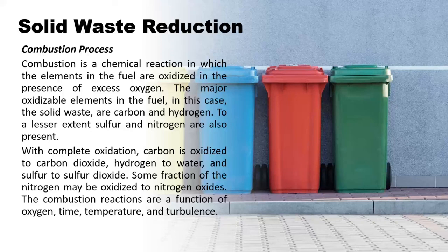Combustion is a chemical reaction in which the elements in the fuel are oxidized in the presence of oxygen. The major oxidizable elements in the fuel, in this case the solid waste, are carbon and hydrogen. To a lesser extent, sulfur and nitrogen are also present. With complete oxidation, carbon is oxidized to carbon dioxide, hydrogen to water, and sulfur to sulfur dioxide. Some fraction of the nitrogen may be oxidized to nitrogen oxides. The combustion reaction is a function of oxygen, time, temperature, and turbulence.